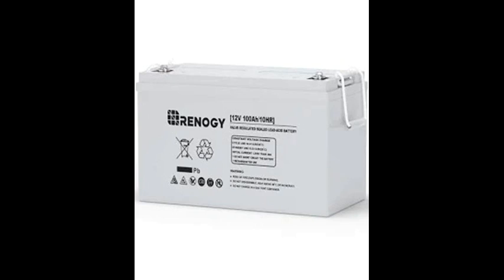And I mentioned amp hours earlier. Amp hours are basically a rating of how much and for how long the battery can provide a charge. So remember, a 100 amp hour battery in theory can deliver 1 amp for 100 hours, or 100 amps for 1 hour, 5 amps for 20 hours, so forth. However, there's more that you need to know to understand the big picture.